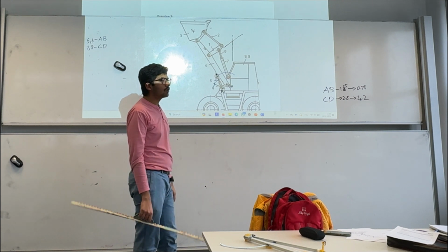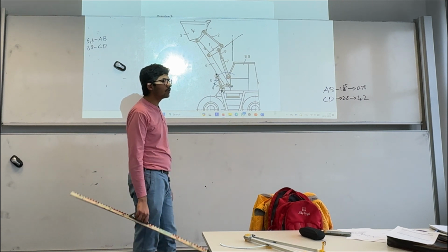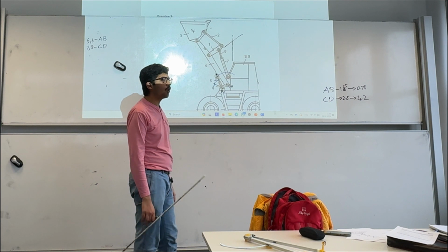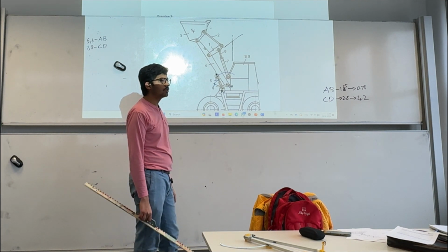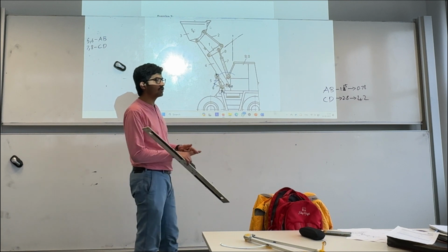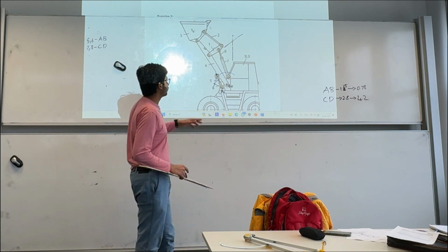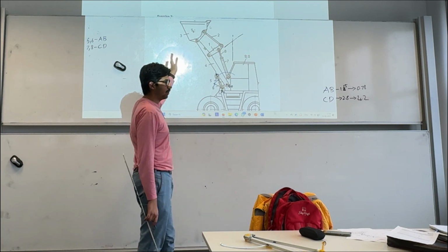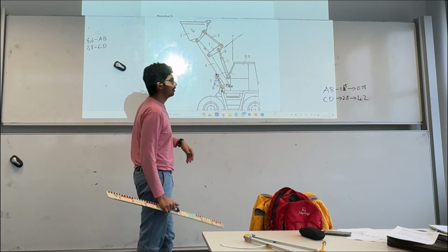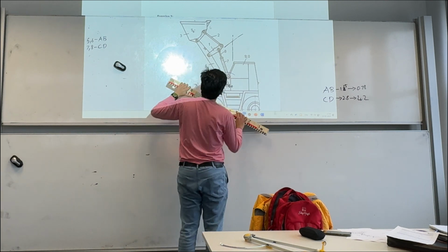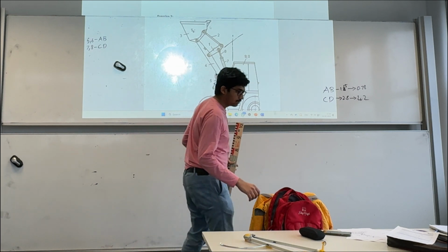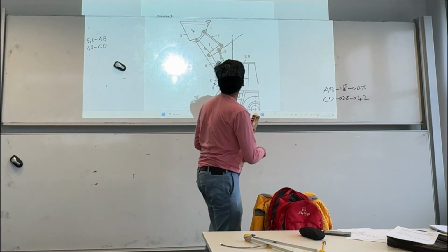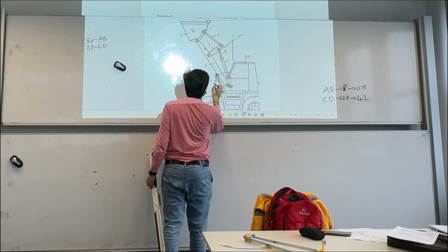So it's not moving along that axis that is the piston, but it's moving along that axis. You always need two arcs and 2 points, because you need two constraints to reach the answer, because you have an x variable, y variable in 2D plane. So the endpoint should be called A2. You did mark it.